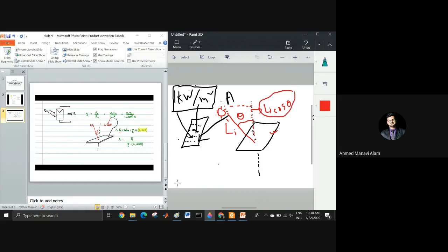So if I summarize what I'm getting, the formula you were using was Vm Im into L into A. But you can't use that formula anymore, because the solar insolation is not directly above our PV cell. A certain portion of solar insolation is on the PV cell.